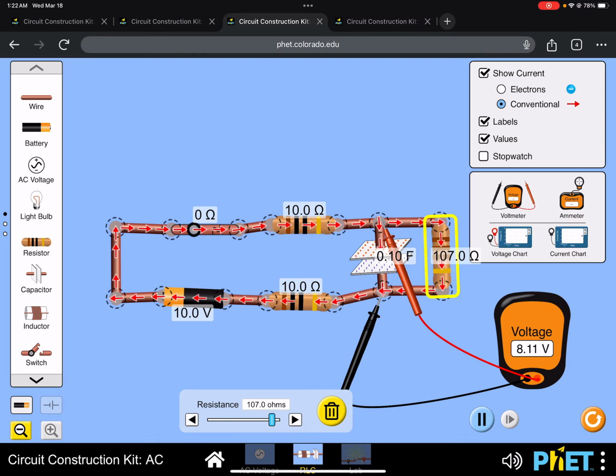right? And if you think about it, this actually makes sense. So as the resistor on the right-hand side gets larger and larger, the voltage drop across it is equal to I times R. These three resistors have to have the same current, right, because they're all in series. Well, once the circuit reaches steady state. They don't while the capacitor is charging. But once it reaches steady state, we see that there's no more current flowing into the capacitor. The three resistors here are all in series. And this resistor on the right, as the resistance increases, it has to have a larger voltage drop than the other two resistors.